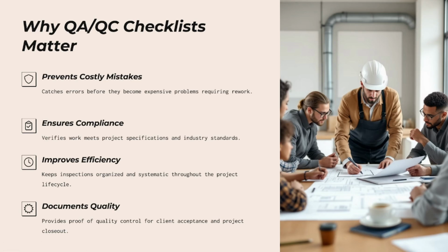So why do QAQC checklists matter? Why is a checklist now mandatory for any inspection? The first is to prevent costly mistakes, the second is to ensure compliance, third is to improve efficiency, and fourth is to document quality. Preventing costly mistakes means they catch errors before they become expensive problems and recurring reworks.